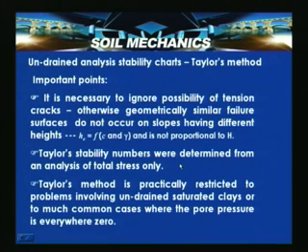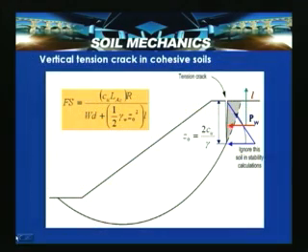Some attempts have been made to use it for effective stress, but in such situations it leads to serious errors. In such situations, Taylor's method is practically recommended only for problems involving undrained saturated clays, or cases where the pore pressure is everywhere 0. Now, let us look at the previous case in the circular arc analysis.